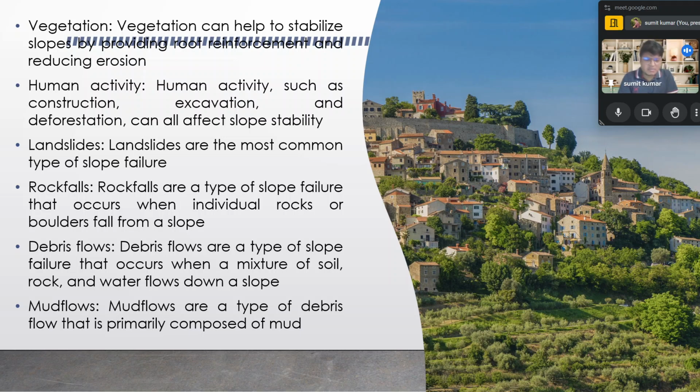As you see from the image here, many constructions take place along the sloping ground as we go from the upper section to the lower section. There, the slope needs to be stabilized, and the vegetation is also clearly visible at the specific cross section. So, this vegetation could help to bind the soil, creating a bond between soil particles, so that it could reduce the chances of failure.